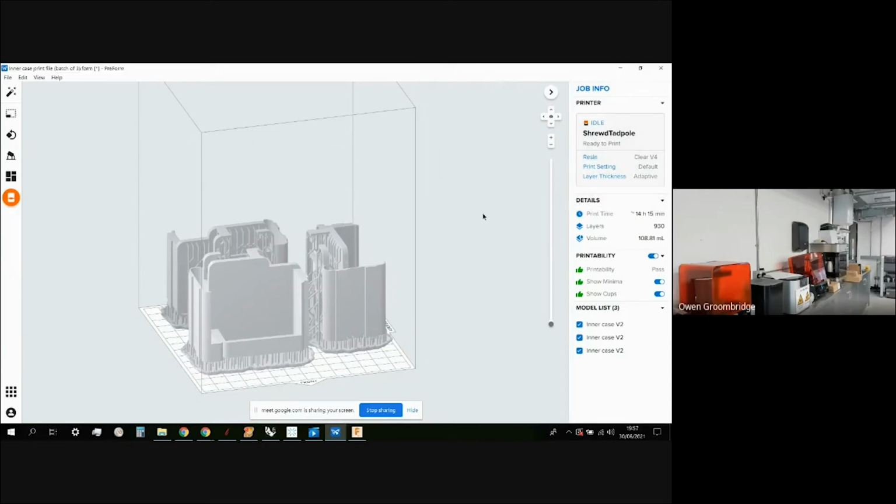Okay. Now, the thing to bear in mind when you're printing anything with PreForm is that you tend to need support. We very rarely print directly to the build plate. And the reason is that certain things are very difficult to get off the build plate, especially if you're printing in something like ceramic. Ceramic is incredibly hard to get off that build plate, as Ian knows very well.